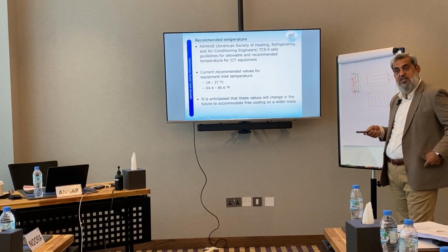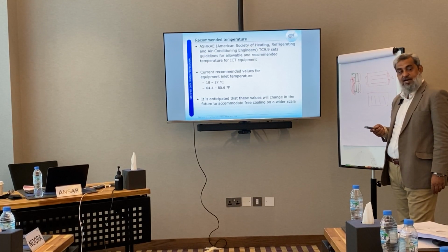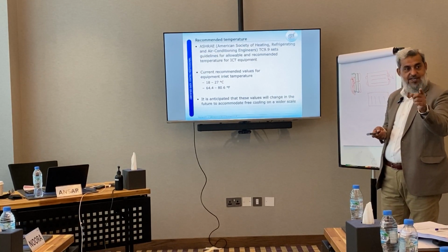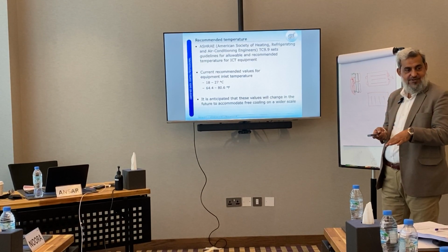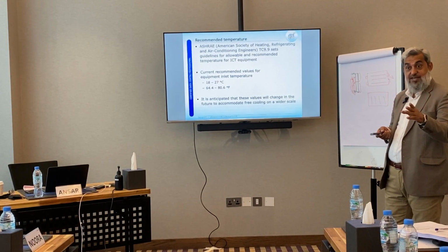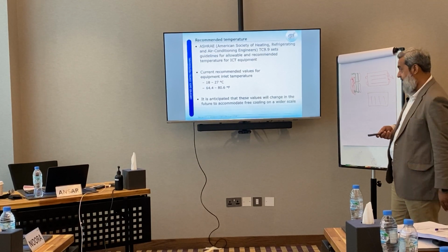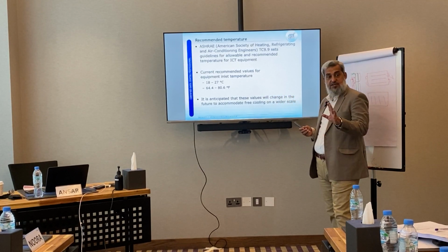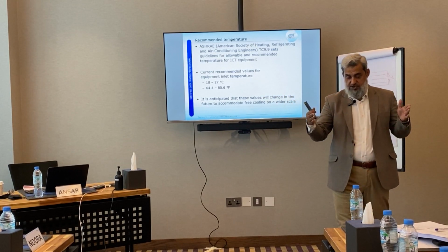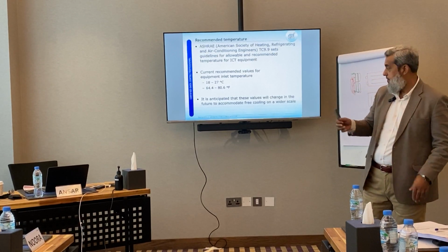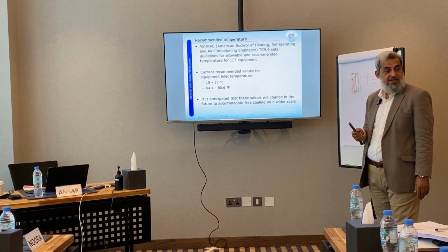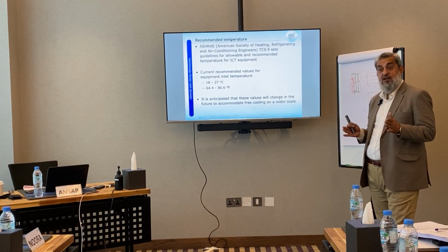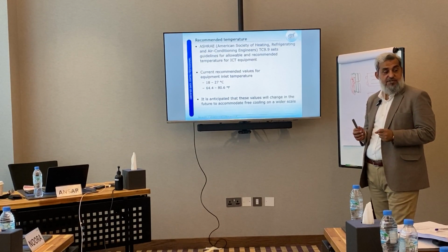because they work very closely with EIA, Electronic Industry Association. So if you know the TIA 942, the full name is TIA EIA 942. So Telecom Industry Association, Electronic Industry Association, and then 942. So the current recommended values for equipment inlets in the data center, remember this point where we need to maintain the range of temperature, is 18 to 27 degrees centigrade. So we should maintain the temperature between 18 to 27 as per the ASHRAE guidelines for the data center.